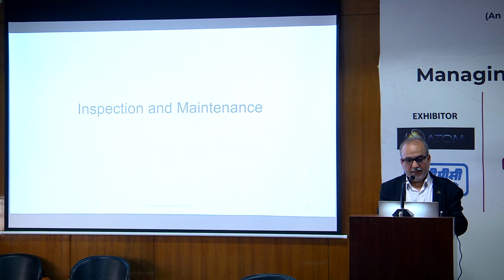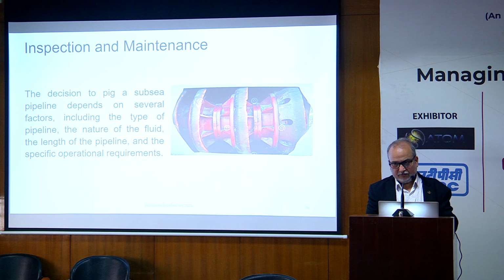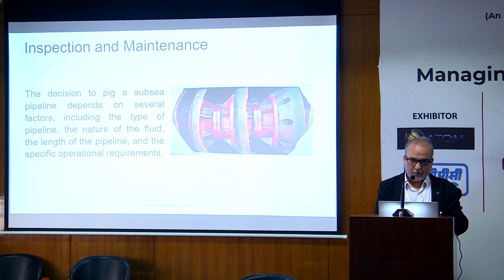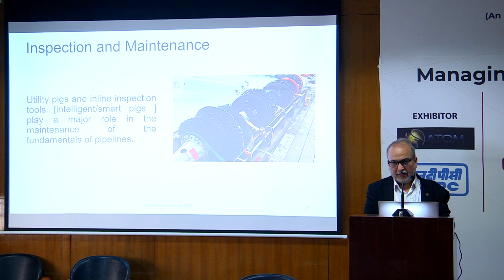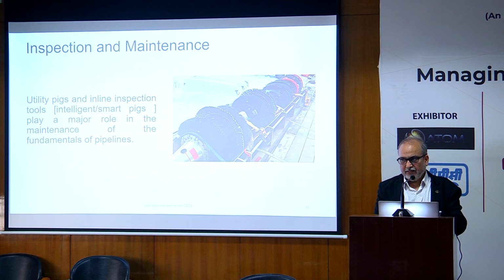Inspection and maintenance practices are as applicable for onshore pipelines. We are also following similar practices, pigging and intelligent online pigging, for the pipelines. But subsea pigging is a challenging job because of infrastructural constraints.